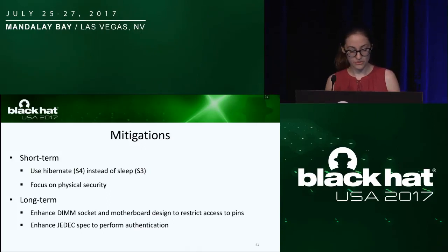And as a long-term solution, we were thinking that it would be a good idea to change the DIMM socket and the motherboard design so that those pins are not accessible. Even if our attack might prove not to be possible, you're still exposing some information there because you can read the signals out and get information from that. Another mitigation we have thought of is to add some kind of authentication in the JEDEC spec, so the DIMM will not blindly trust whatever memory controller is trying to communicate with it.